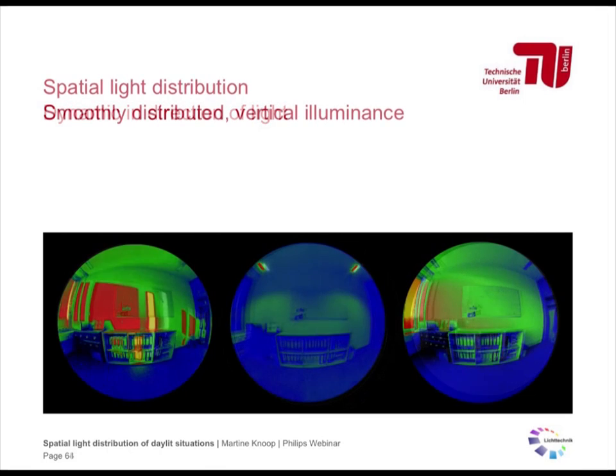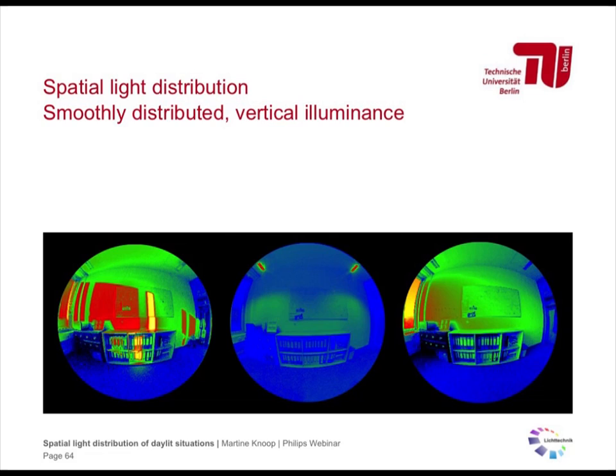So when it comes to vertical planes, which seem to be important for user preference, daylighting has this already by default. I have some luminance pictures here as well. I need to point out that these pictures are definitely not about horizontal illuminances. They do not have comparable horizontal illuminances. It's more about the luminous distribution.